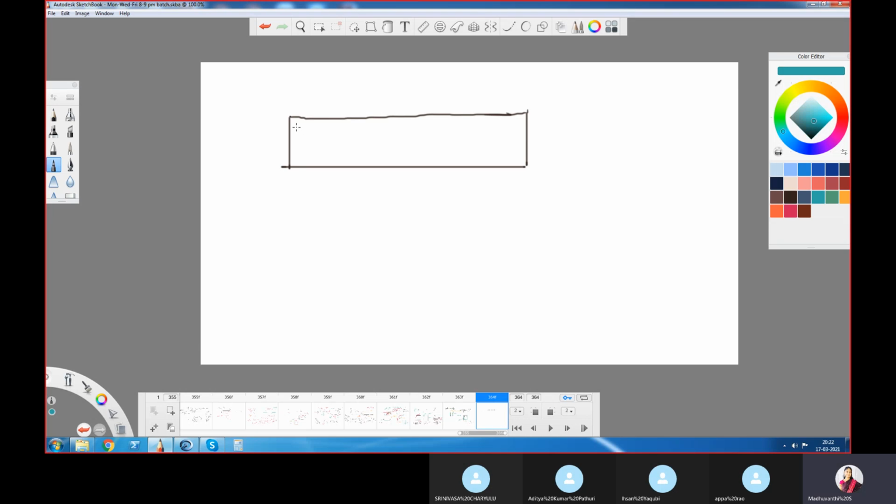To take the elevation in beam design, we would have provided the bars like this. This may be three bars of 25 mm diameter running throughout like this. And here a few bars, for example 2 of 25 mm diameter, may be extended only up to this tension zone, up to some distance.